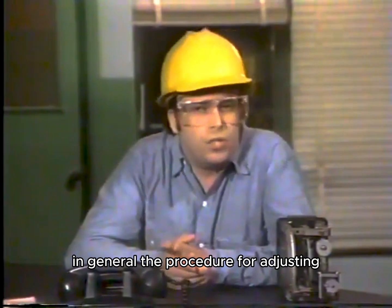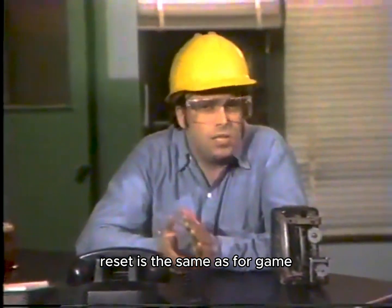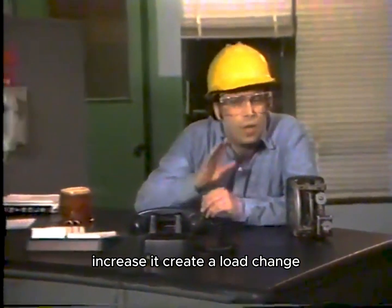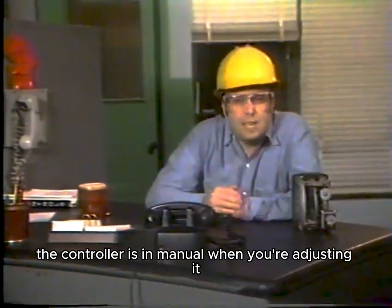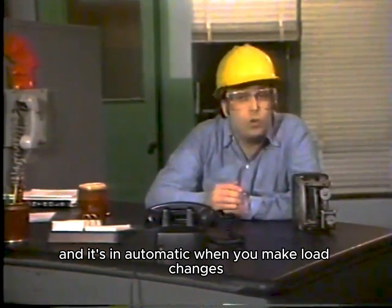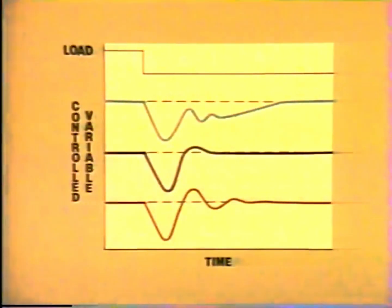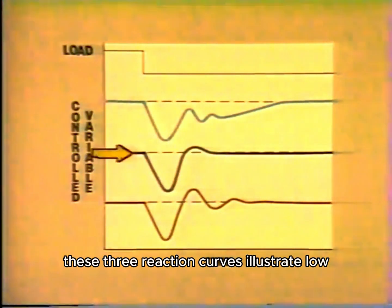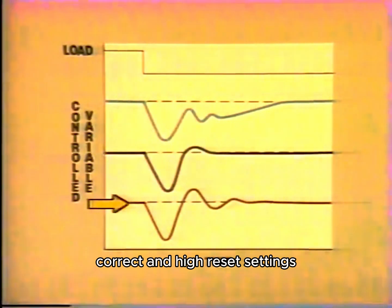In general, the procedure for adjusting reset is the same as for gain. Increase it, create a load change, then observe the reaction. Remember, the controller is in manual when you're adjusting it, and it's in automatic when you make load changes. These three reaction curves illustrate low, correct, and high reset settings.